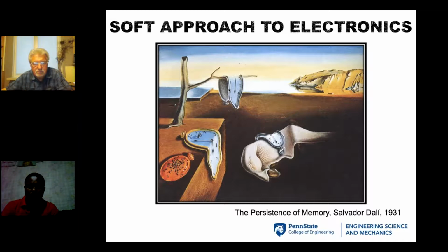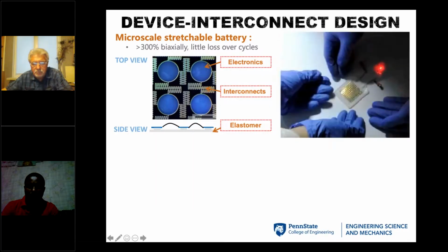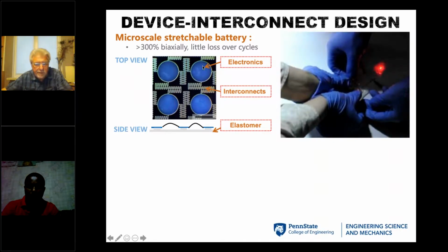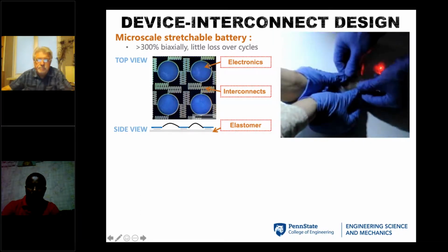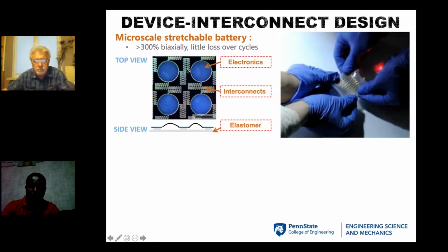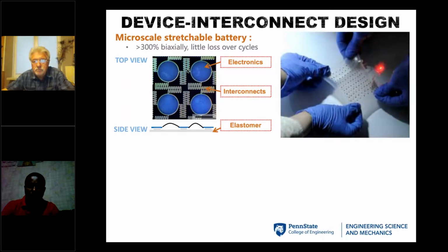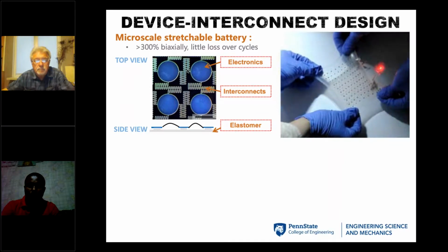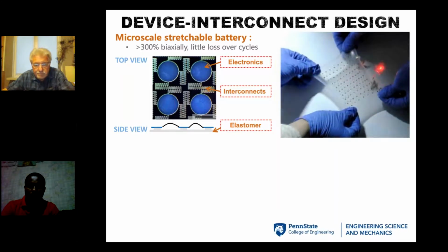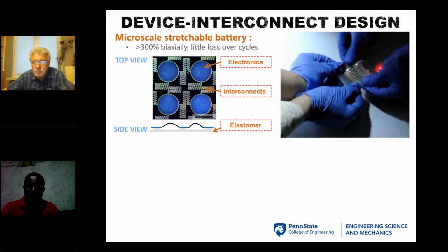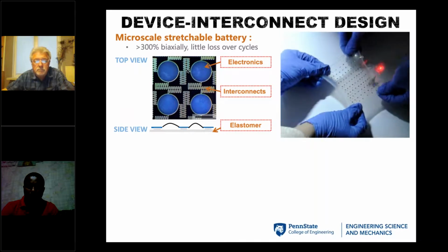And in terms of design, we have a simple technique, which is to have these devices break into smaller pieces, and then they are interconnected through the wavy geometry, pretty much like the spring we used to play with in daily life. And if we think about this, it's really something trivial, but it can actually enable the structural property for the entire system. Think about the straight wire: it is not going to be stretchable if we have a single wire in a straight geometry. But if we design it into a serpentine geometry, we'll be able to stretch it into a larger area.